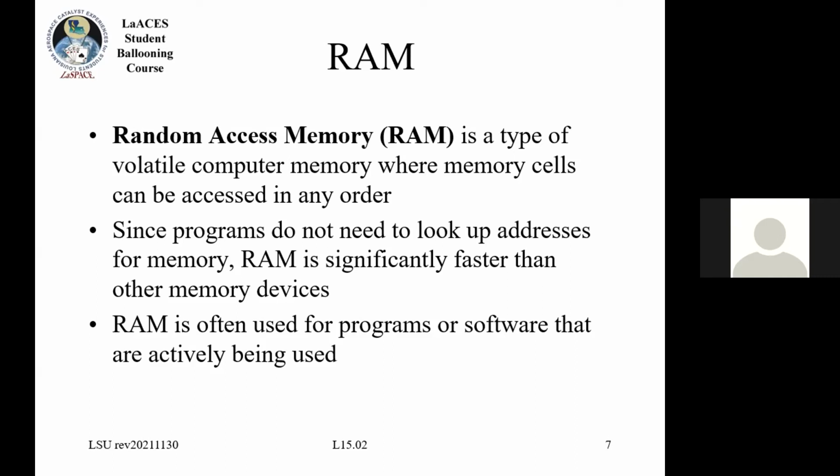And that's useful for programming because it allows you to dynamically allocate variables and say, oh, this data is going to be sitting at this address in the RAM. Also, it's generally going to be very quick read and write because this is what's talking directly to the CPU. This is where we're doing CPU math operations, so we want it to be fast.